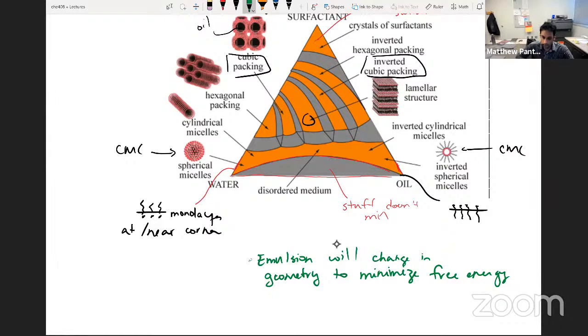So you can see that the effects of this are interesting because you can get these structures that resemble solids, like with this cubic packing that extends in 3 dimensions. And that's where you can get these solid-like structures that can hold their own shape, right, from 2 liquids, essentially, with a small amount of surfactant, meaning less than 1% surfactant in there. And the surfactant itself can also be liquid. So you can take 3 liquids, mix them together, and make something that has a structure that resembles more of a solid. So as engineers, that is really interesting, right?